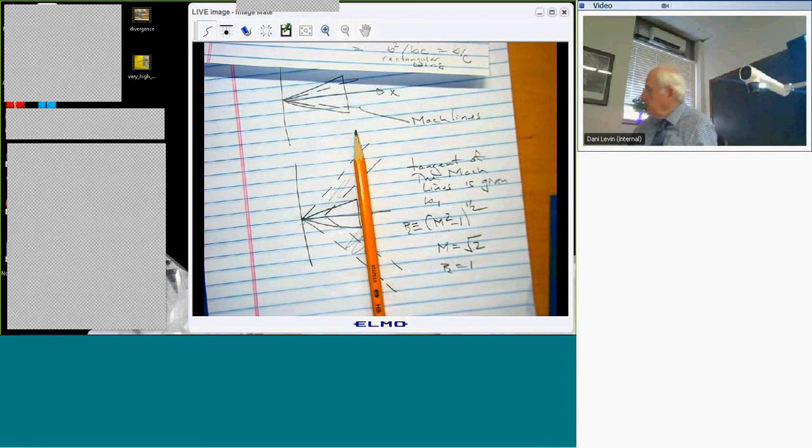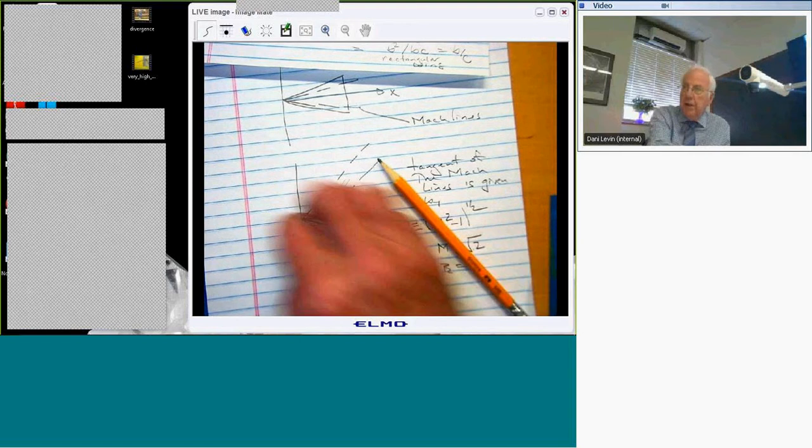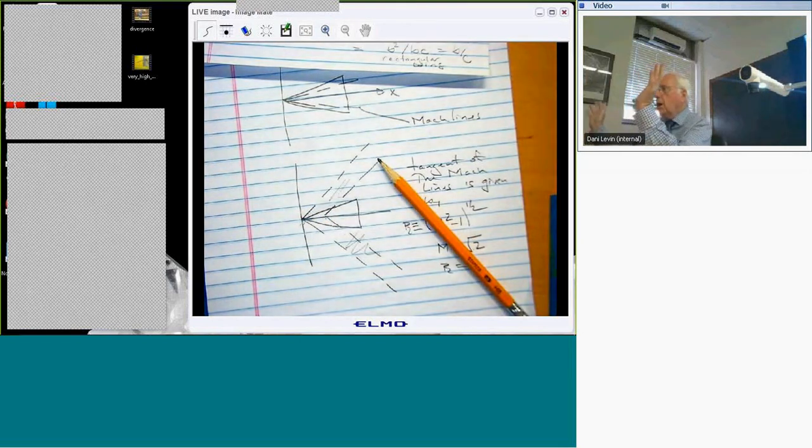Is that clear? So supersonic leading edge just means, for a given geometry, it's when the Mach number gets high enough that the flow off the wing isn't disturbed ahead of the leading edges of the wing. And it's easiest to see for a delta wing. If you have a more complicated geometry, you have to kind of go along the leading edge and see how the Mach lines go and make sure everything is lined up. For a delta wing, it's easier to explain. That's why I usually draw delta wings. Also, they're easier to draw. My drawing ability is very poor, so I can usually draw a triangle on a good day.